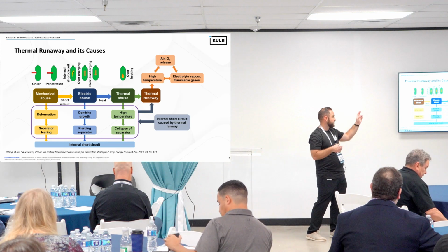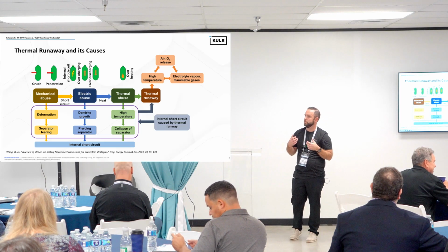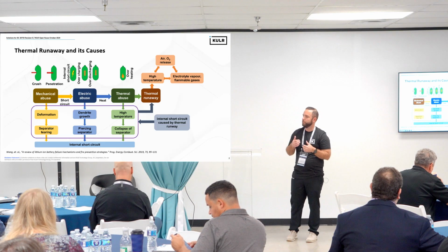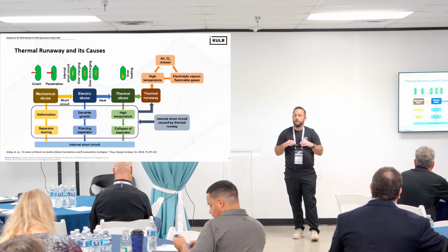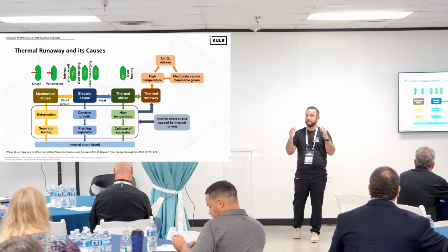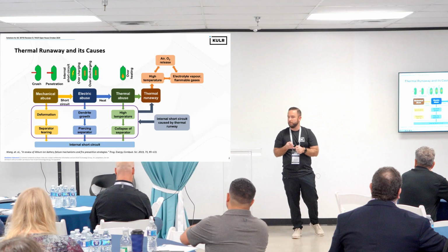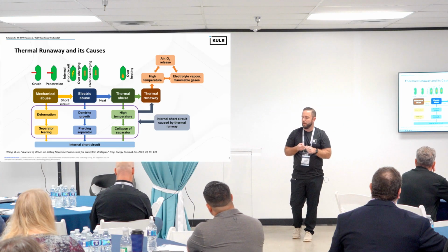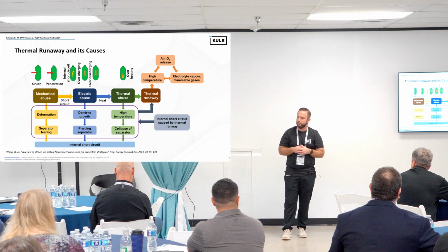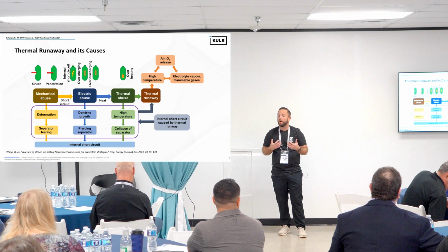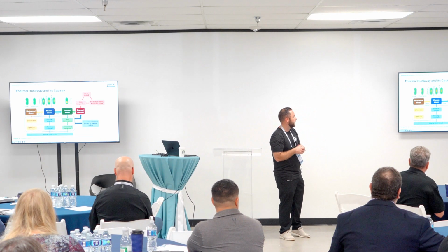So when you talk about thermal runaway, if you start at the right-hand side and work your way back, we're talking about the rapid exothermic decomposition of the materials within the cell that drive temperature rise within the cell at such a rate that eventually that cell loses thermal stability. It eventually ruptures. We have flame, ejecta coming out, solids, liquids, and gases come out of the cell. We can have secondary combustion events that happen as a result, whether there are nearby combustibles available or the materials coming out of the cell mix with the gases and ignite them. We have additional combustion events which add energy and fuel to the system. So that's what we're talking about when we talk about thermal runaway, but there's a lot of things that can actually lead to thermal runaway occurring.